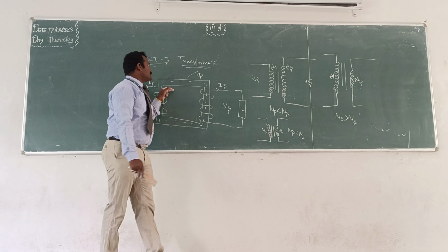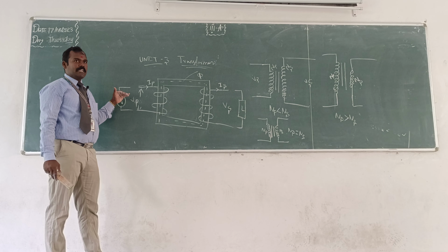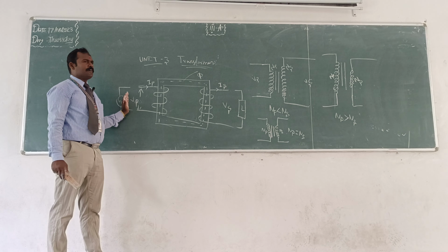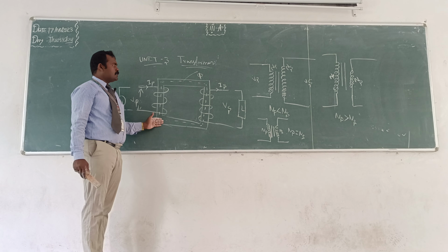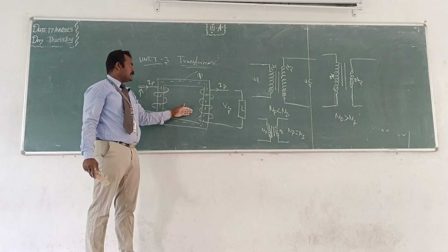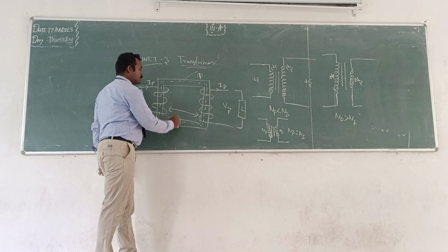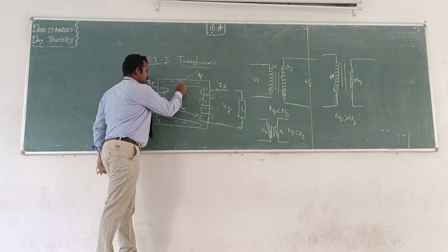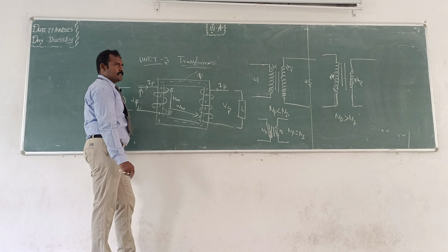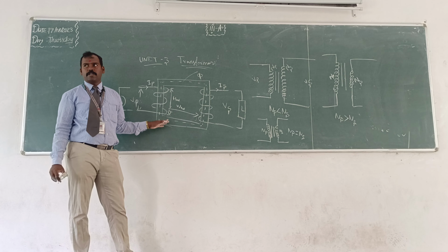In this particular unit, from the electrical machine design point of view, we should select the transformer based on our requirement. Then we can use it for either step up or step down, with the number of turns in the primary winding and in the secondary winding. Then there is the window: the width of the window, and this is the height of the window, HW, right? The width and height of the window are the main dimensions of the transformer. That also we are going to find out.